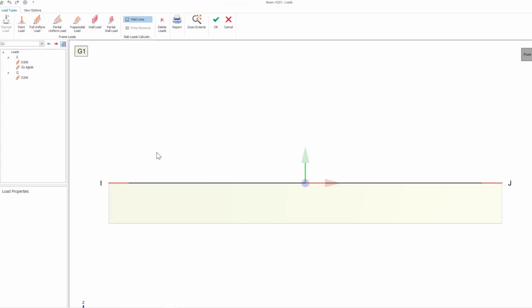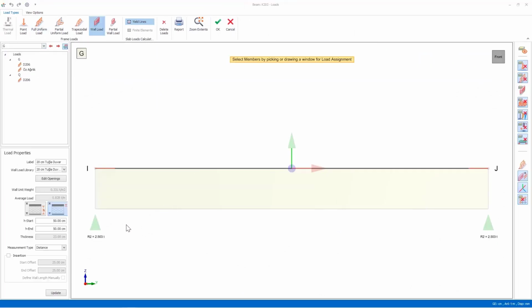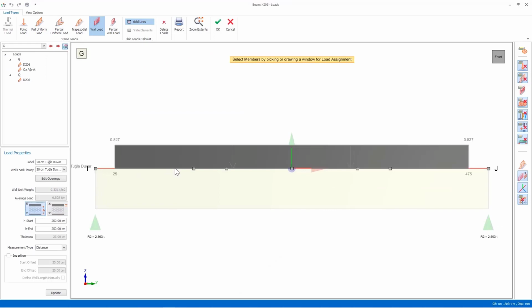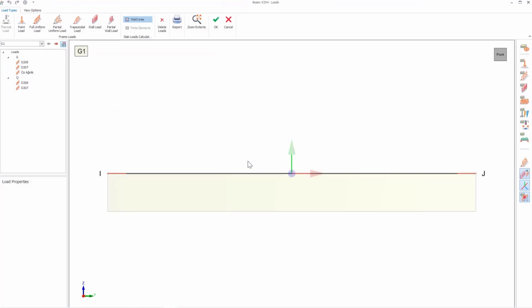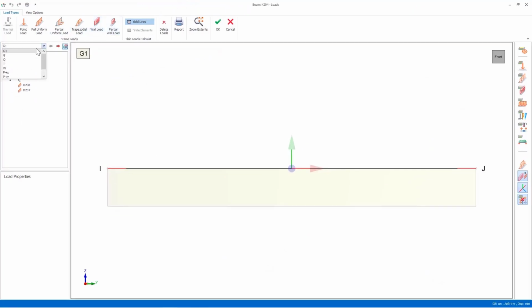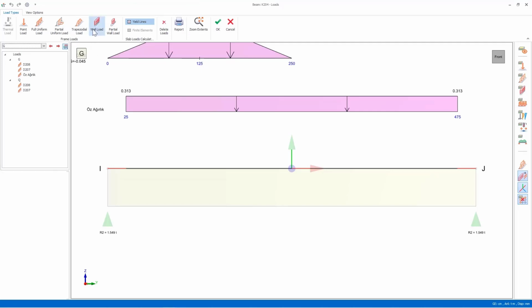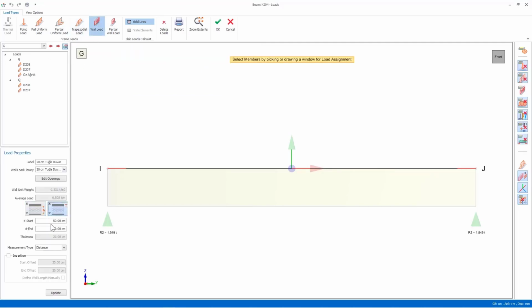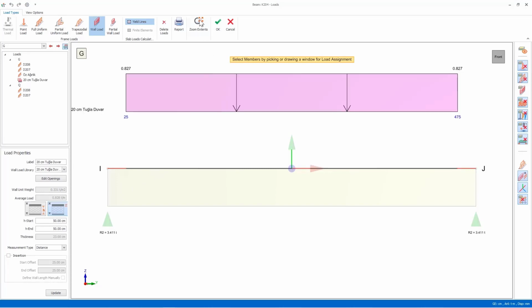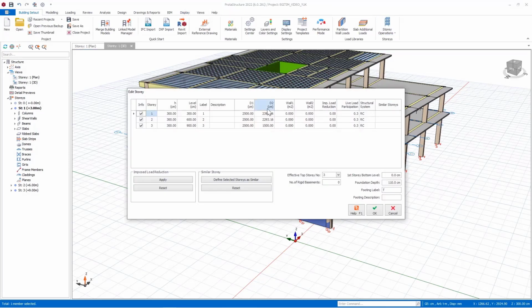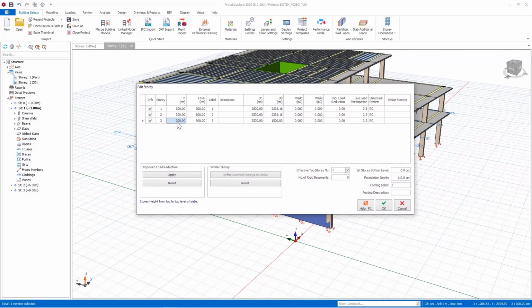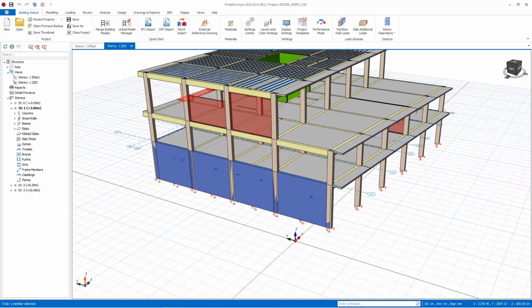Let's exemplify this. Let's define one of the beam wall loads, the first method, and the wall height by manually entering values h-start and h-finish. In another beam, let's define the wall load by entering the relative distance from the upper floor in the d-start and d-end fields. Now let's change the floor height. As you can see, the two wall loads behave differently from each other. The difference between these two methods can be explained in this way.